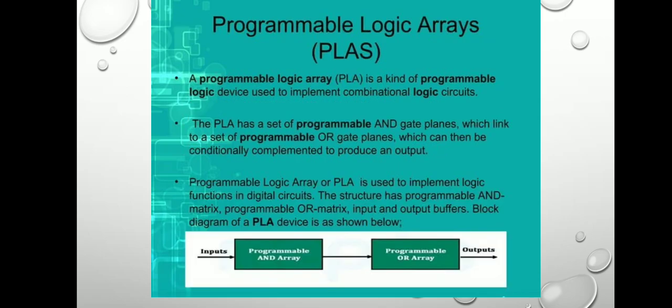Programmable logic arrays have a fixed architecture with programmable AND gates followed by programmable OR gates. It is a type of programmable logic device used to build reconfigurable digital circuits, and its function is undefined at the time of manufacturing, but it is programmed before being put into use. In comparison, the PLA has a programmable AND gate and programmable OR gate. The PAL has a programmable AND gate but a fixed OR gate. In the ROM, it has a fixed AND gate, but a programmable OR gate array.